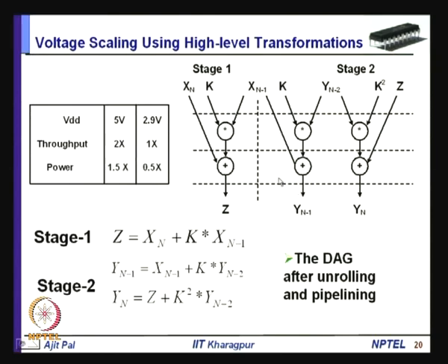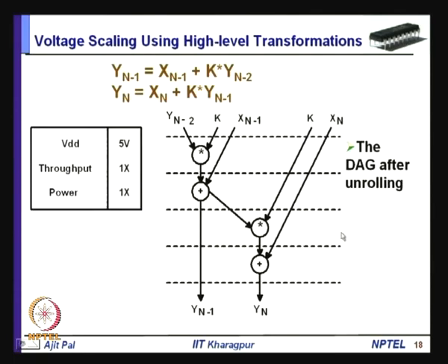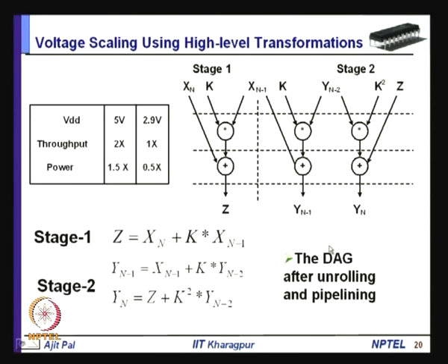That means, you have got two options again here: either you can do the computation and produce the result quickly, or you can reduce power dissipation by scaling down the supply voltage. So, here is the result for that. Whenever you do voltage scaling, the time to produce these outputs will be the same as that required in this circuit. So, whatever time is required, 4 clock cycles, the same time is required here.